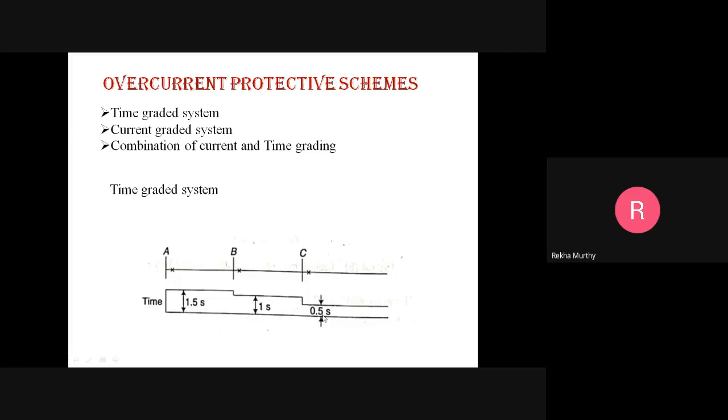If the fault occurs near the power source, it involves a large current, hence it should be cleared very quickly. But this scheme takes the longest time in clearing the heaviest fault, which is undesirable because the heaviest fault is the most destructive. So this scheme is suitable for a system where the impedance between the substations is low.